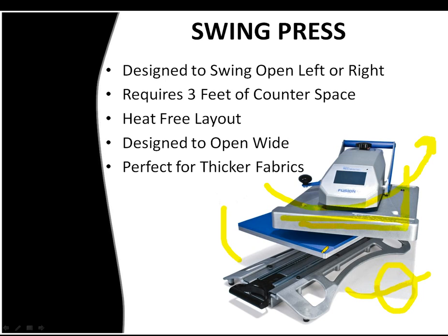The swing press and the draw press, which we're going to talk about next, are perfect for garments that require layout. If you're laying out names, numbers, you know, anything in that department, jerseys, t-shirts, anything, especially for sporting goods, a swinger or a draw type press is the type of press that you're really going to want, because you're not going to want to be doing layout work underneath that heat that you're going to get with a clam type of machine.